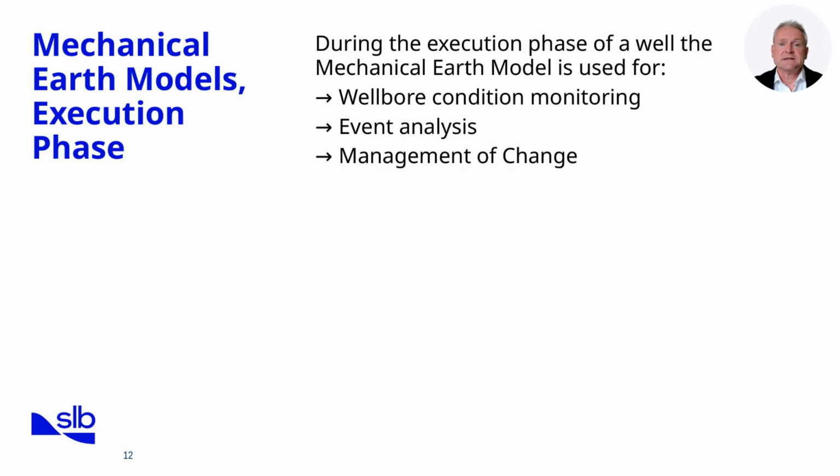Event analysis is another critical application. When issues arise, such as unexpected losses, tight hole, or stuck pipe, the MEM provides a framework to diagnose the cause. Was it related to pore pressure variation, stress orientation, or an underbalanced mud column? By tying events back to the model, we learn and refine future decisions.